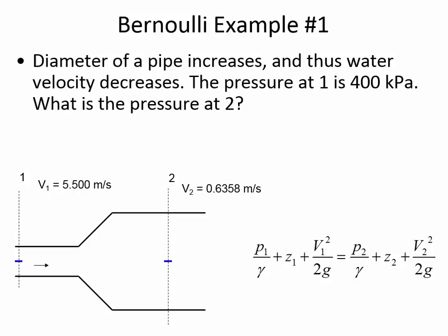Now, we're not accounting for turbulence in Bernoulli's equation because turbulence is a kind of energy loss. You're envisioning in your mind a lot of swirling turbulence, right? Like vortices and eddies there. Yeah, it'll cause that. But it's not like there's going to be air in there because of those. It's not going to introduce air because there's lots of turbulence. But there would be energy loss, and Bernoulli's equation would do a worse job of predicting what's happening for a rapid transition than it would with a smooth transition. You can still use it, but it just does a worse job.